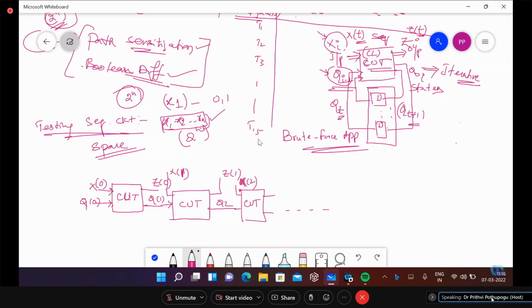Now what is in time scale, that sequential, is converted into space. X of t represents the input in time, whereas X of k represents it in space. If you can convert that, the majority of the complexity in testing your sequential designs is gone. That means complexity-wise you are cutting down. This is very simple, and analyzing this is very simple.